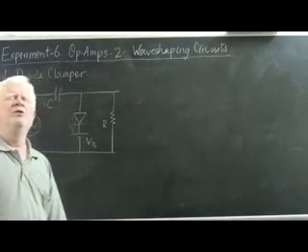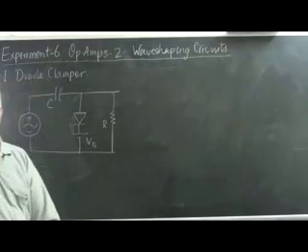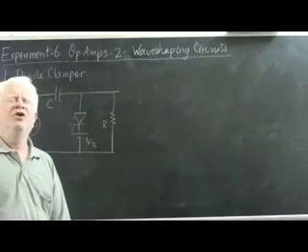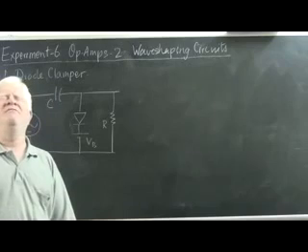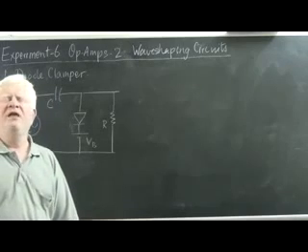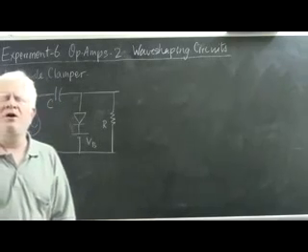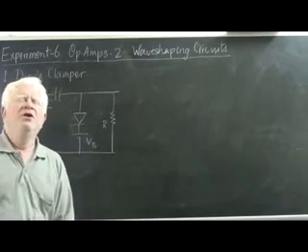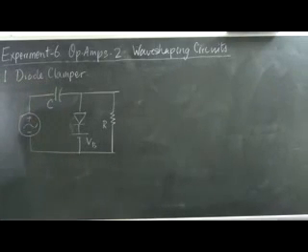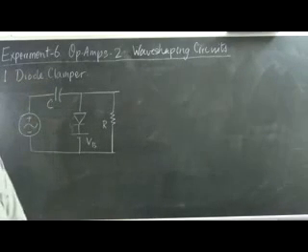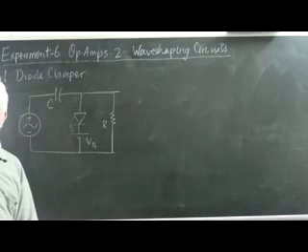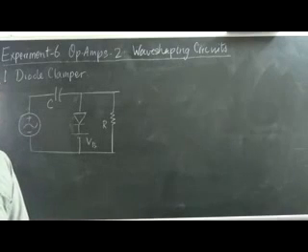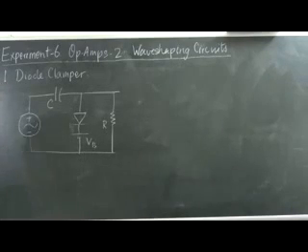With the clipper circuit, all you will need to do is to see how the clipping function varies with the changing of VB and VB dash, and observe and superpose both the input and output signals on the scope to clearly see the clipping action. You will also be able to detect the difference of 0.7 volts between theory and practice on account of the non-ideal behavior of the diodes. So that's about the diode clipper.